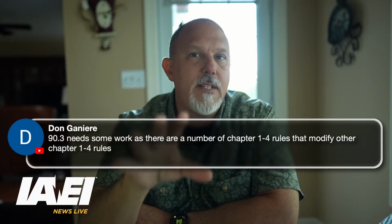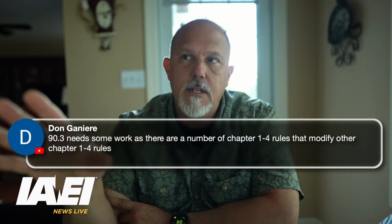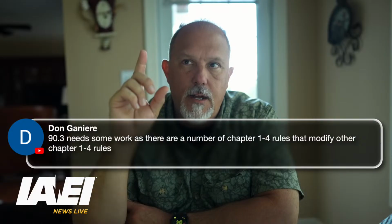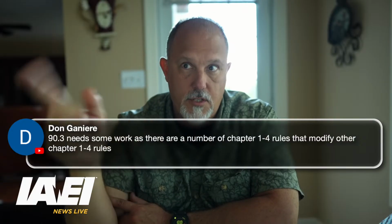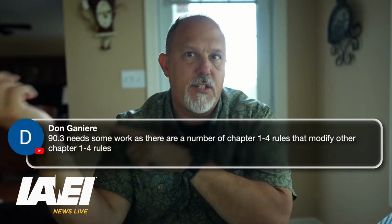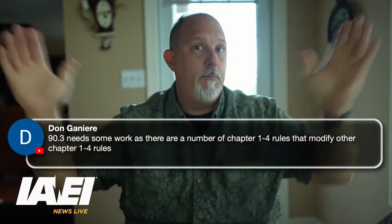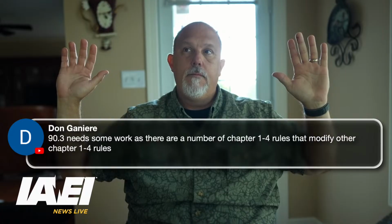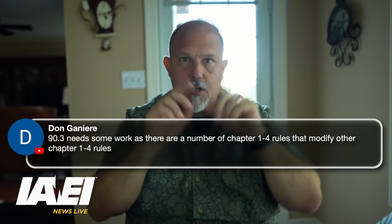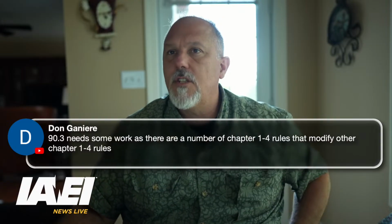But honestly, Dawn, I think that if you just said a single motor that is continuous duty is a continuous load based upon the full load currents as determined in Article 430, period. The moment you say it's a continuous load, you're going to do 125%. Now let's go back.